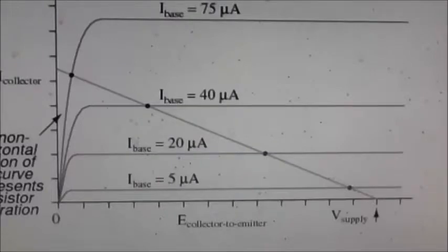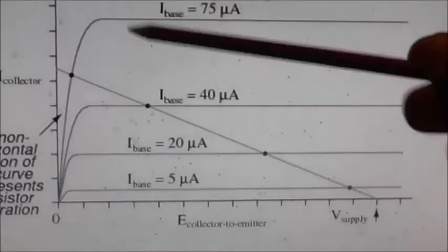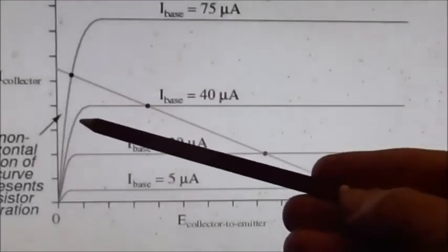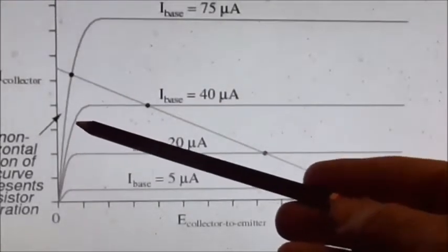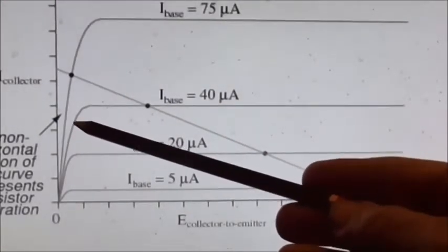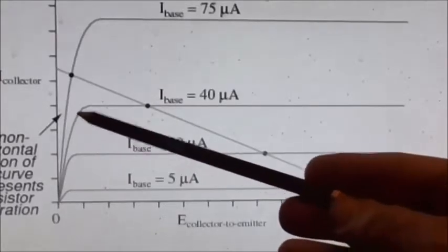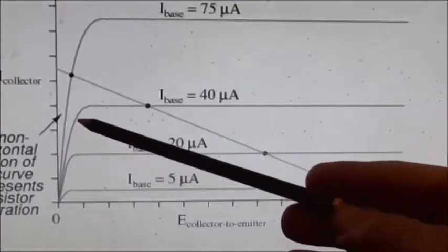And of course the question now is, how is this going to help us decide what resistor to put in there? Well, if we look at this load line analysis, what we did when we made the amplifier was we biased it about there, somewhere below the knee. And that gave it the freedom to swing up and swing down without clipping.